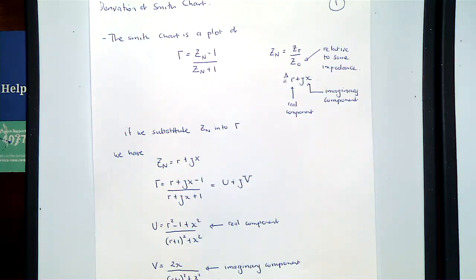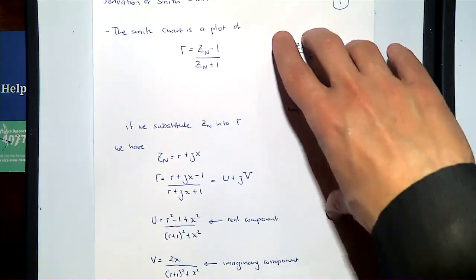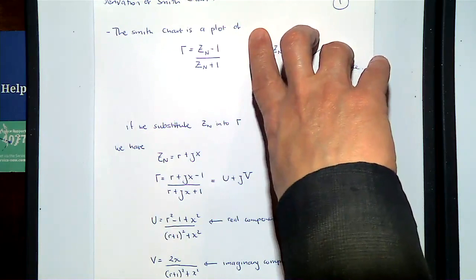Notwithstanding that, Smith charts are an extremely important way of representing impedances. And most importantly, if you're making measurements using a vector network analyzer, in most cases what it does is draw the impedance on a Smith chart. Now, with that prelude, I'll go very quickly through the derivation of a Smith chart.